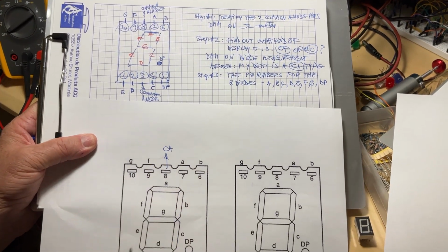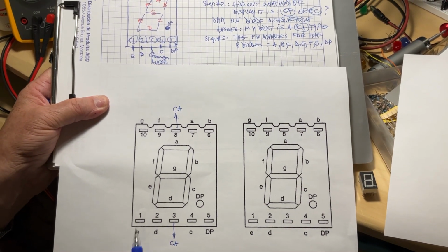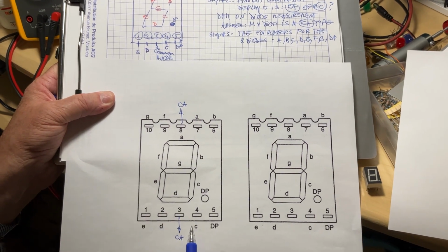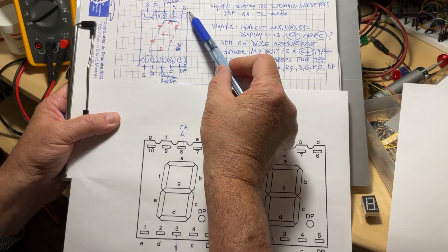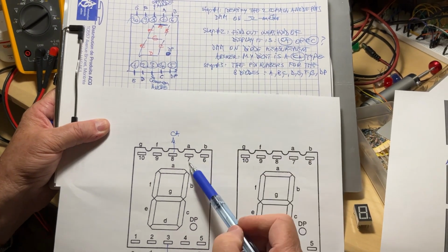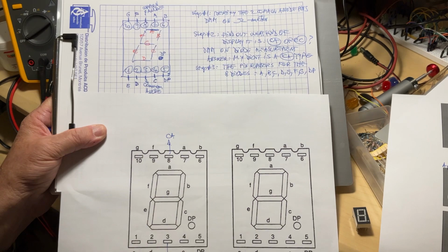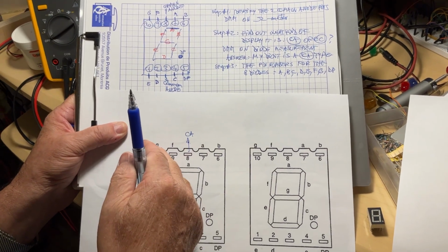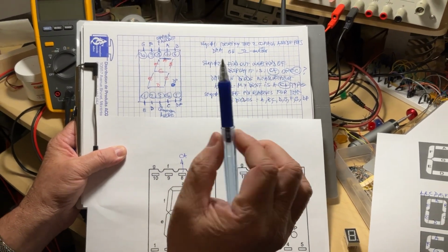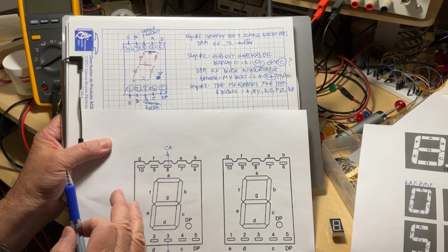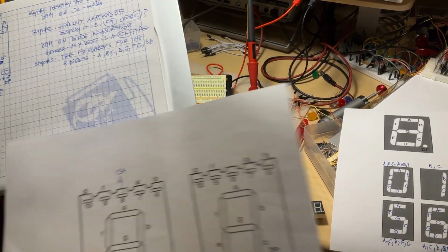Pin 1, segment E. It doesn't matter that they use lowercase; the letters are still the same. Pin 2, segment D. Pin 4, segment C. Pin 5, the decimal point. Pin 6, segment B. Pin 7, or terminal 7, segment A. Terminal 9, F, and terminal 10, G. So this is from the manufacturer. But again, the method I just gave you in 3 steps allows you to identify any such digit regardless of the manufacturer, okay? Now, let's go further.